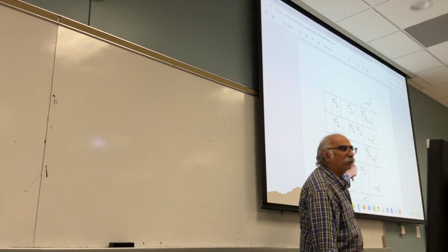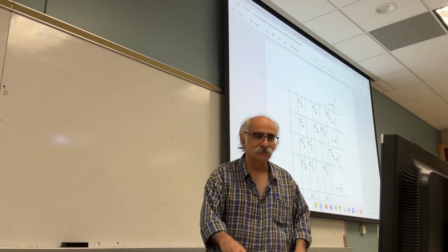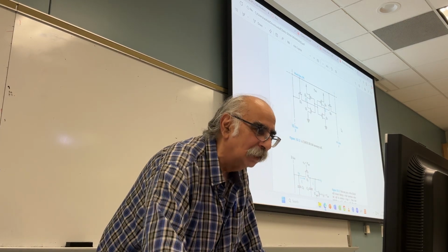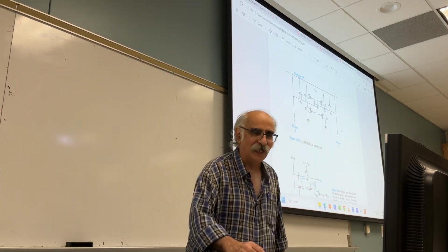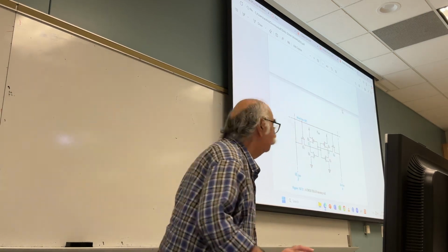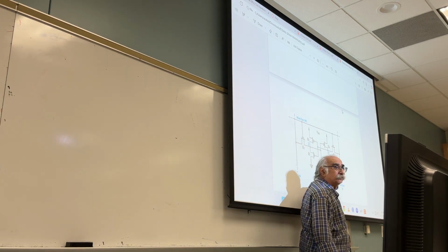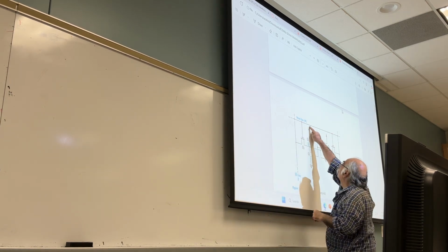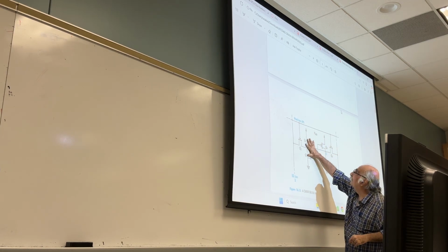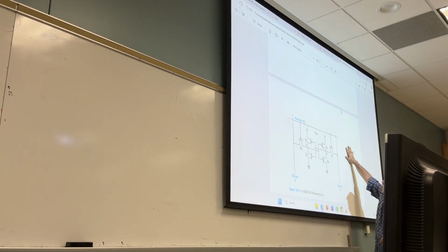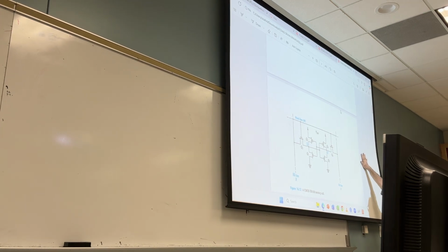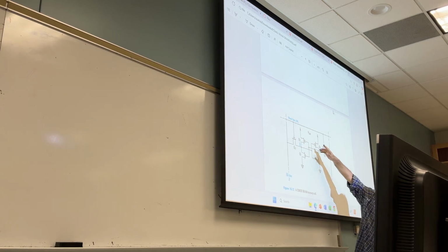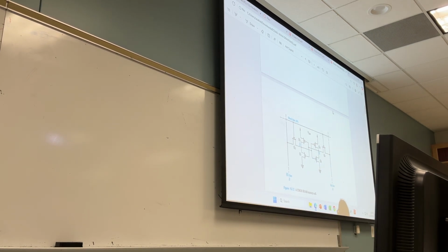Okay, this is the decoder. The word lines are these, and the word lines are going to control the access transistors, which are Q5 and Q6. That word line will activate this cell, the next cell, the next cell, all the cells in the same row. They are all connected to that word line.